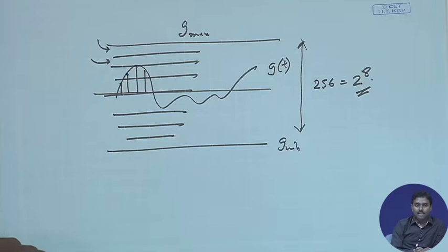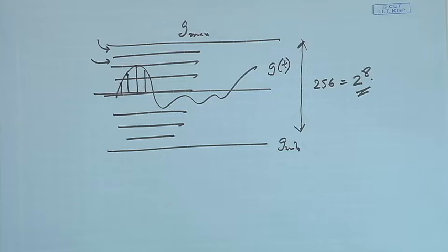So if I take 8 bits, and my signals are binary, taking only 1 or 0, then with those 8 bits I can represent 256 different patterns. This is already known to you. All 8 zeros will be one pattern, seven 0s with the last one 1 will be the next pattern, and so on. You can represent up to 256 such patterns. Wherever this sample stands, I can immediately say it is in this particular range, which has a code in the binary representation.